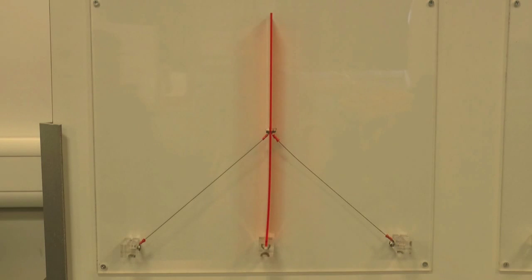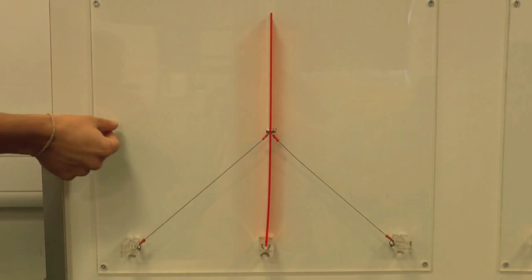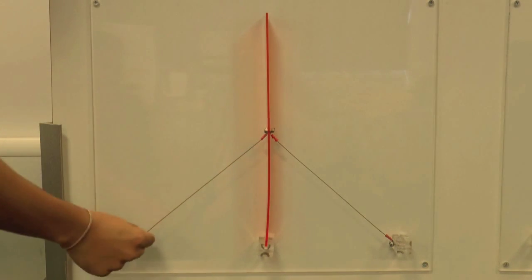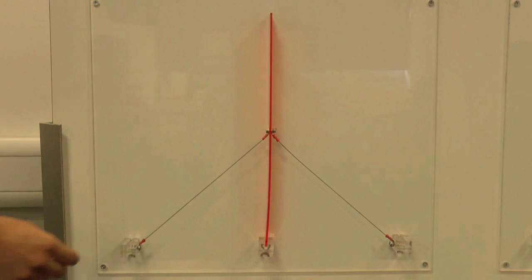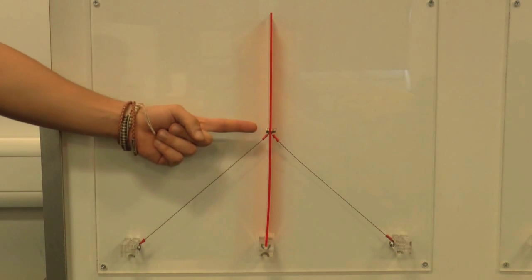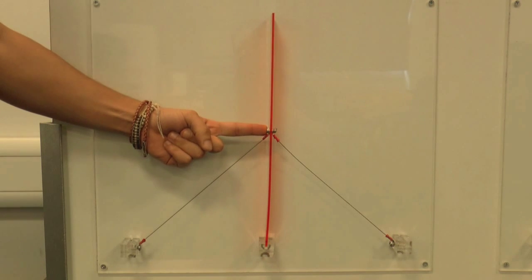The model we looked at previously didn't give a real life indication of the mast. See, the mast had yard arms spanning horizontally that were connected using cables to lower yard arms. Now, why do we have these cables? If you imagine a yard arm applying a lateral force on this point, you can see as I apply force, we see no bending at the mast.